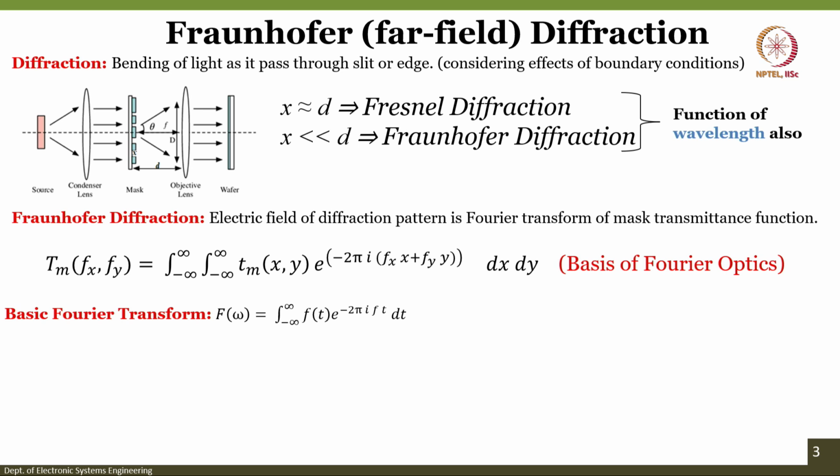Now, the Fourier transform, generally what we have studied so far, is a function that can change one domain into another. Majorly, when we are dealing with a time domain signal, we convert it into the frequency domain, and there are some properties of the Fourier transform which all of you should know, like the duality property. A time limited signal will have infinite frequency components. A band limited signal will have an infinite time domain.